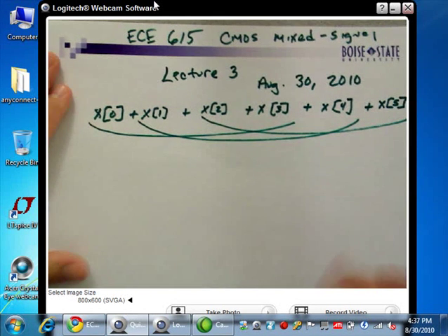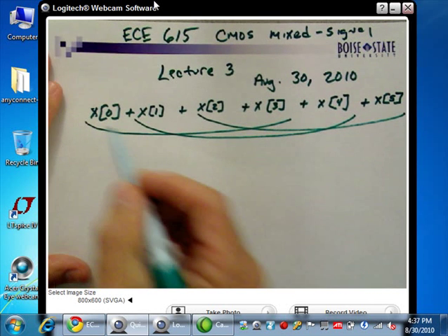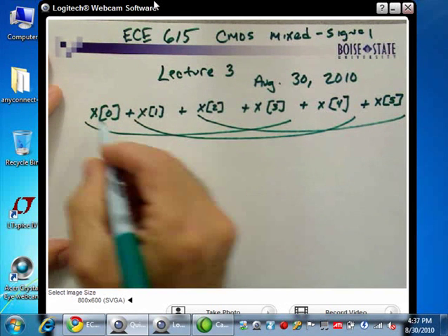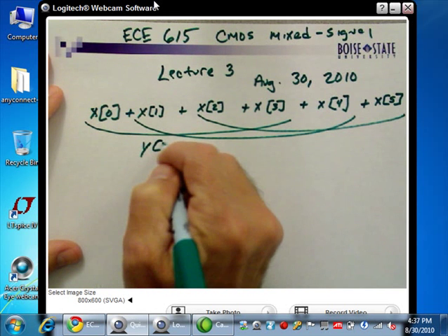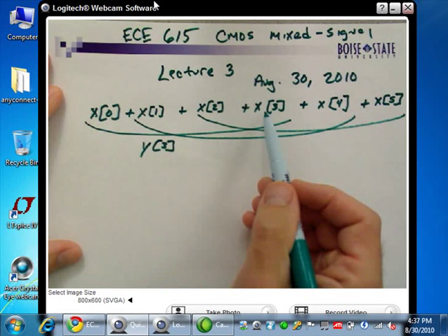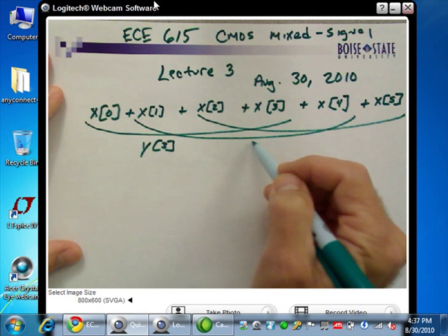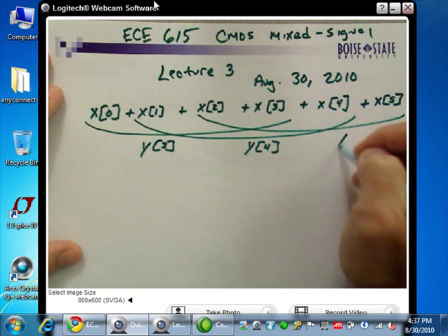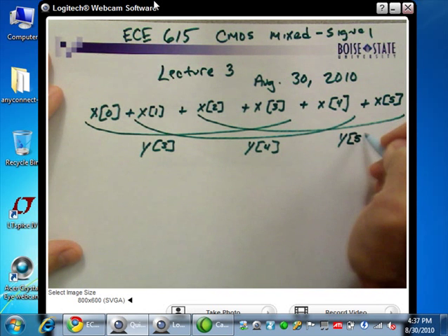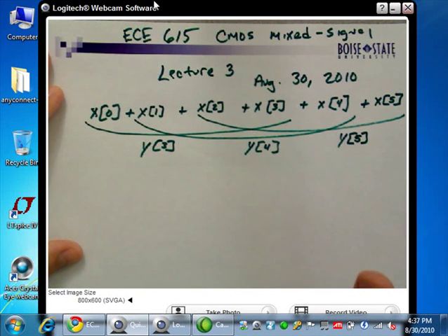I'm boring you. So my output would be the sum of these 4, which would be, let's say y of 3, because I have to wait for all the samples to go through. The next output would be y of 4, and the next output would be y of 5, etc. Does everybody follow?